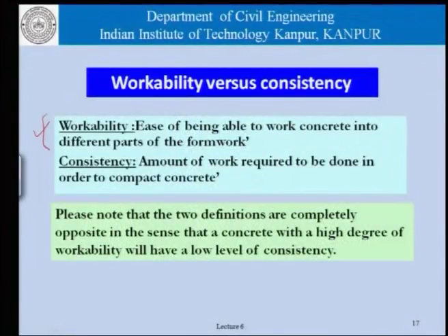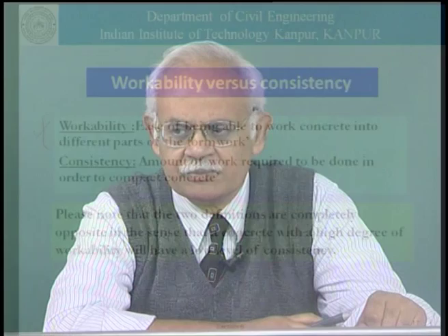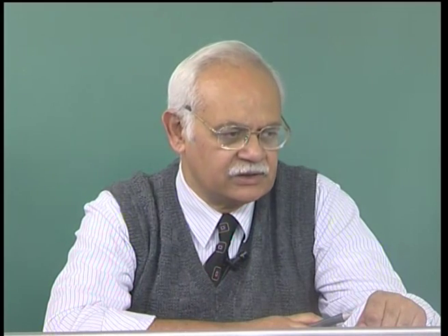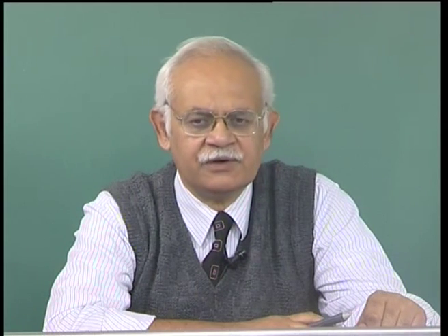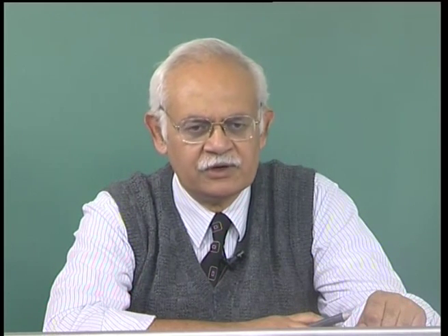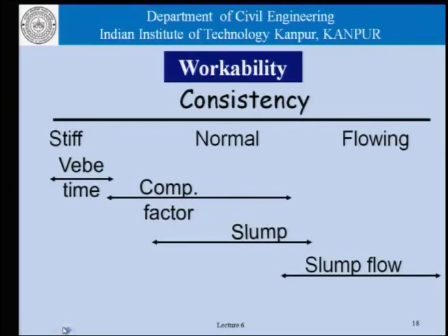As far as we are concerned, not only in the discussion today, but also during the course of the different lectures in this course, we will follow this definition of workability. When we say that a concrete is highly workable, we mean that it is very easy to work with. When it is harsh or less workable, the concrete requires a lot of work to be done in order to compact it or in order to make sure that it occupies the different corners in a formwork and so on and so forth.